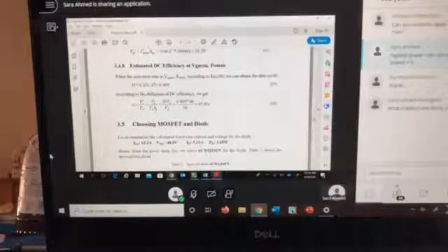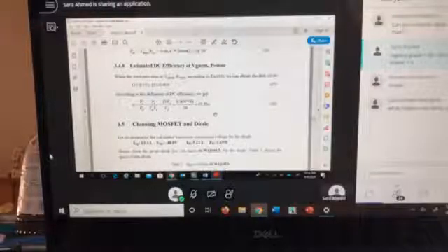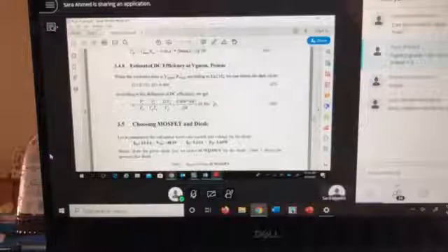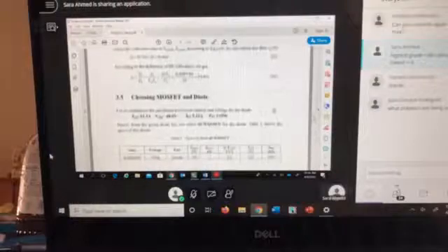And then from this one, you can actually simplify it. So in the end, you end up with about 93.8. Again, this number might be a bit different, but it should be the same if you're using those nominal values, because it depends on the duty cycle, which all should have the same value for the duty cycle. It depends on the output and input voltage. So you should get the same efficiency on here.